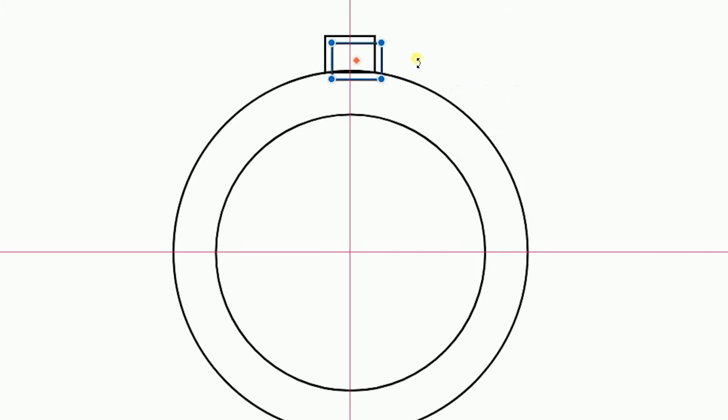But because I already damaged my sequence, I need to start again. So Ctrl D, then position the point, then hold Shift key, and let's say I want to set it to 30. You see, angle is 30. And then Ctrl D over and over again.